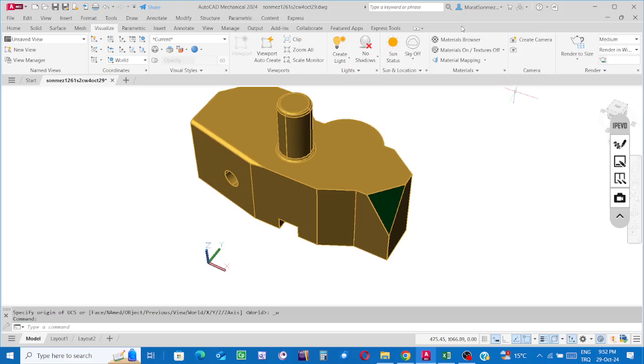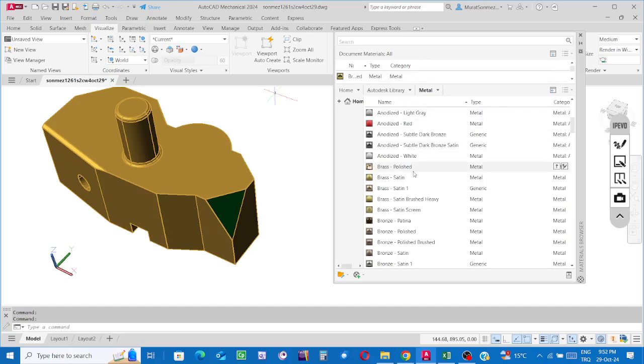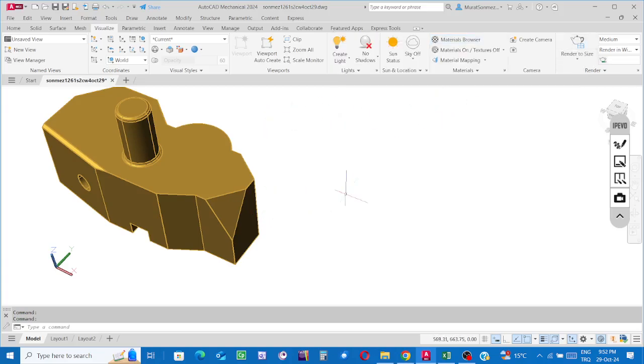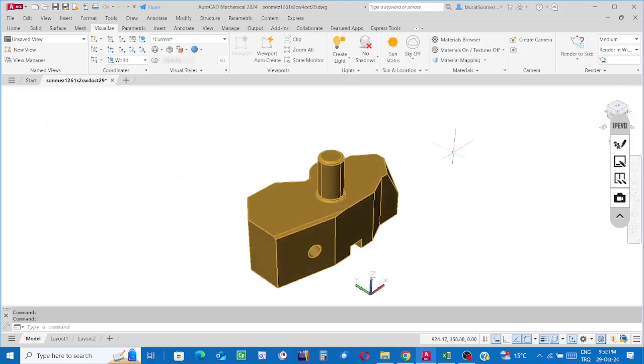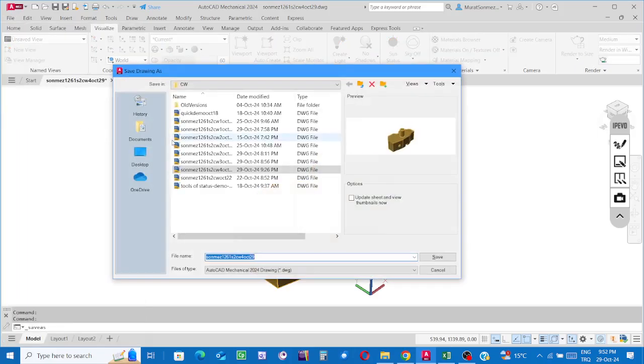It is green. We need to assign the material for the surface as well. Hold the material option, press polished, and drag the mouse toward the surface and release the button. Okay. Here is the oblique surface. We managed to answer the question of how an oblique surface is created. Okay, save the file. Saying classwork 5. Save as. Okay, classwork 5.